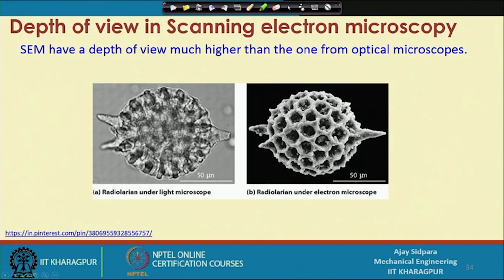Right. This is showing the depth of focus, that means up to what depth you can actually do measurement. This is measured by the light microscope or optical microscope, both magnifications are the same, but here you get the plane only. Now, you can see on this particular plane whatever things are there you can capture, but here the depth of focus is more, because not only that plane, you can get a different plane here, one plane here, one plane here, and one plane here also you can get the information. So, more depth of focus means it will give you a more realistic view of the system or whatever dimension you want to measure, that is possible in this particular case. So, that is the advantage.